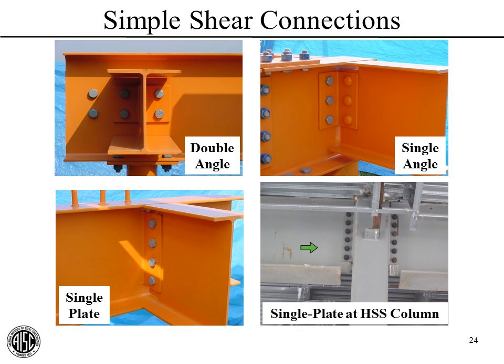Here's another example of a single plate shear connection. There are 2 of these, and they're at this HSS column. And note that the single plate shear connection is especially useful at HSS columns.